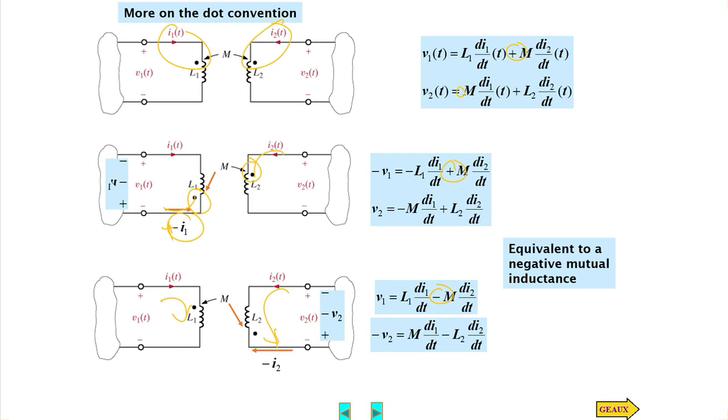Use your own direction of current, and always choose a direction in which this source and this current have the same direction, so you will not have to write these minus signs with it.